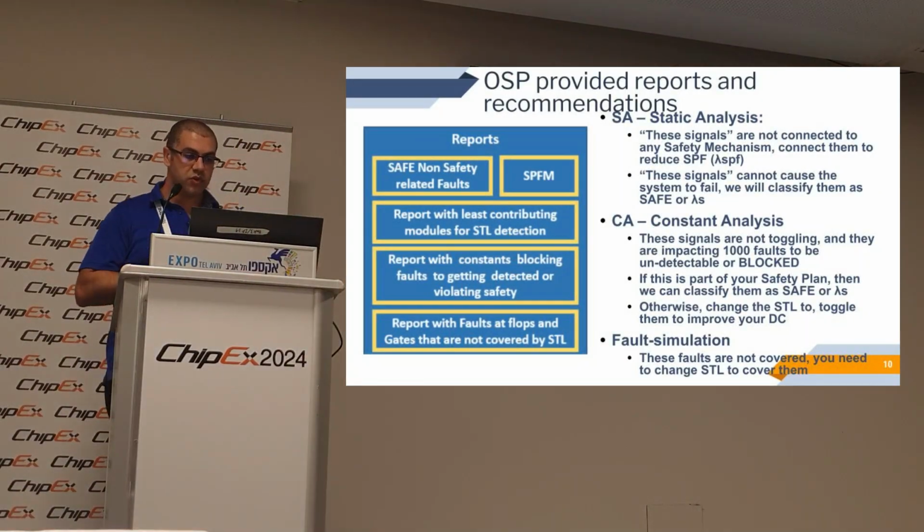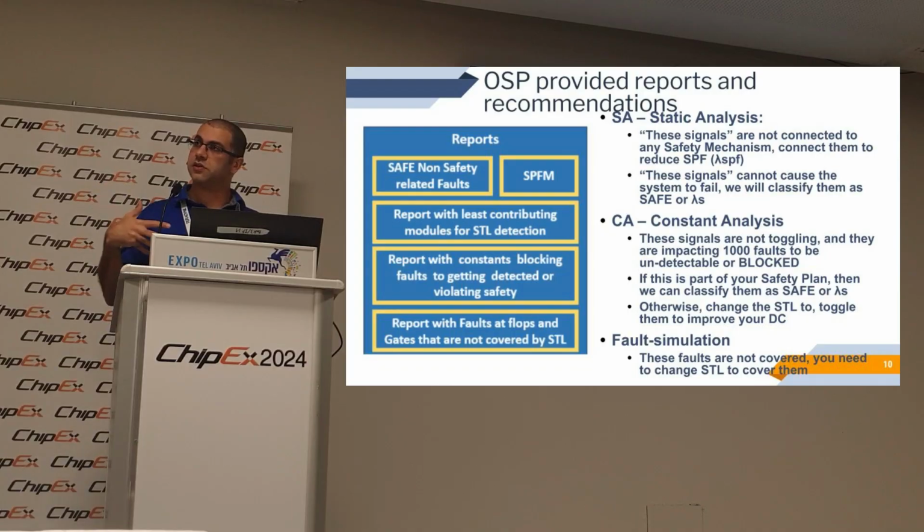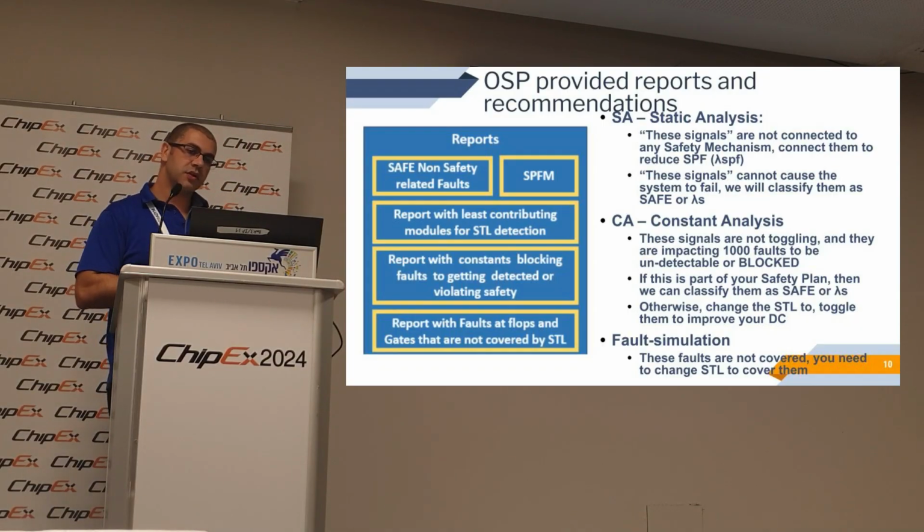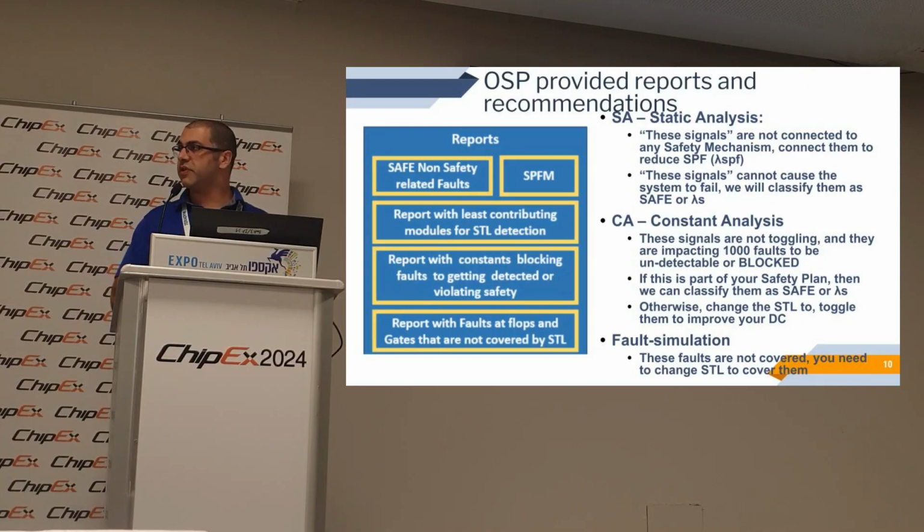And of course, the fault simulation, where we actually inject the fault and run the simulation and see if the safety mechanism, or the STL in this scenario, can actually detect these faults. So the reports, as I said, include insights also from the engines. Besides just the metrics that can be used for the FMEDA report, it also includes insights.